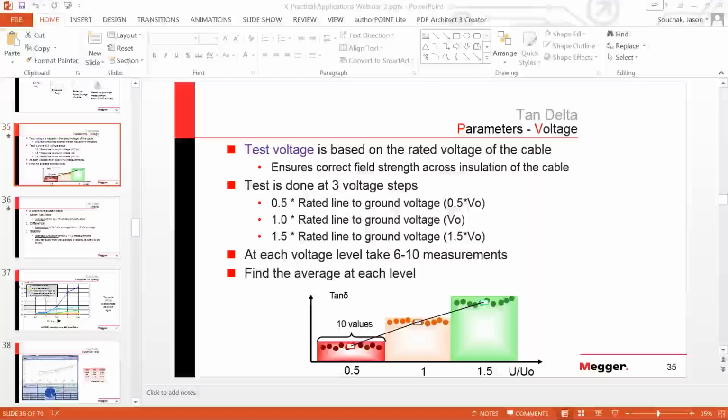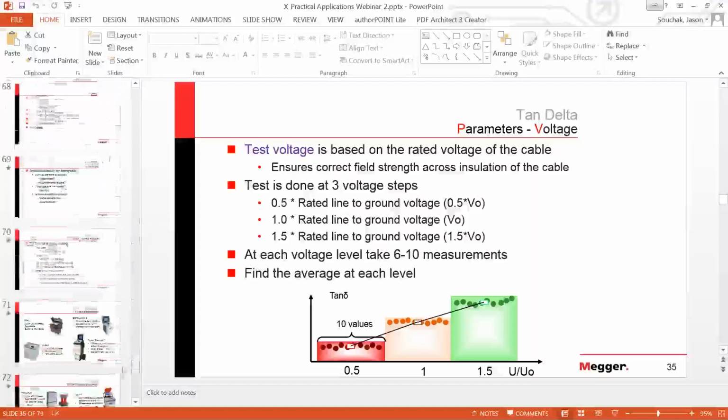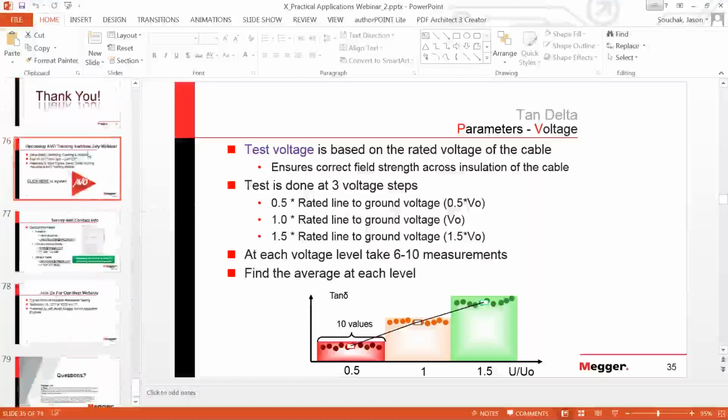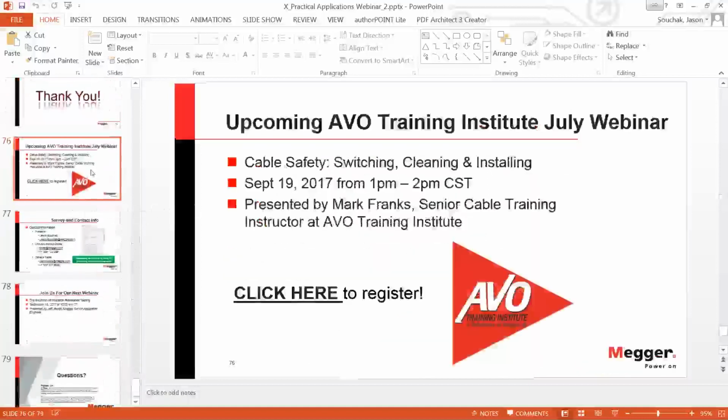They might run in cable trays above ground somewhere. You have UV radiation from the sun, and those cables see the UV during the day, and they have much more temperature change from day to night than a direct buried cable. So basically all these factors together in a given circuit will affect the aging of that insulation system. But temperature is obviously one of the very fundamental ones, and the higher the temperature, the faster the aging will go.